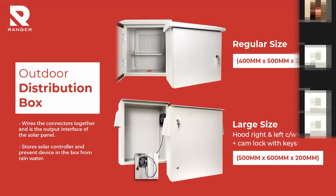I give example for 4 cameras because 4 cameras will be mounted to the pole, and the equipment that will be stored in the distribution box will be the solar controller, LCD display, POE injector, and network switch, based on how many cameras are used.